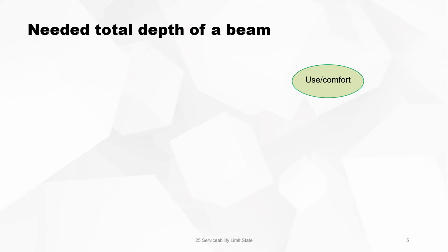The total depth of a beam is based on three main criteria. The first is the use and comfort of the beam. For instance, it's like deflection. If the deflection is too big, it's not very interesting to have a floor with a very large deflection.